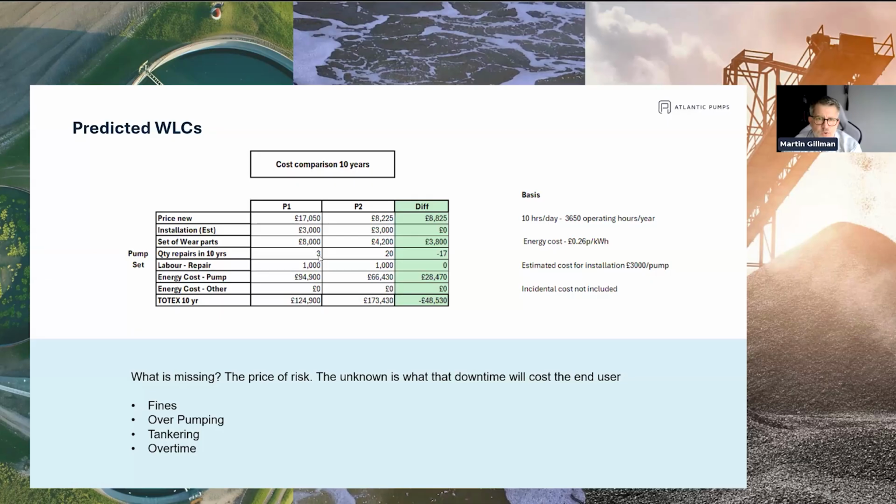Whereas our pump, which has got the correct materials, is running at the right speed, it's going to be reliable. So when we start weaving in the cost of the spares and the maintenance labor, and winding that all together, then we actually start seeing the smaller pump becoming more expensive over a period of time. That's what we mean by whole life cost: it is more than what you just get on your data sheet, or even on your whole life cost sheet, which you might be sent.